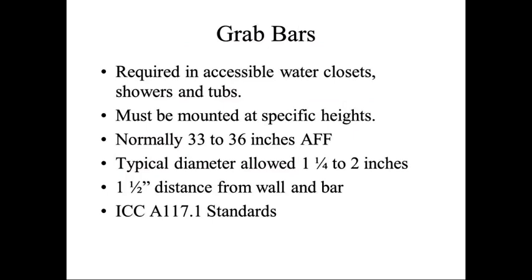Grab bars, we could spend a whole day on trying to look at the normal height of grab bars and the dimensions. So look through there, knowing that your typical diameter is 1 1/4 to 2 inches and 1.5 inch distance between the wall and the bar.